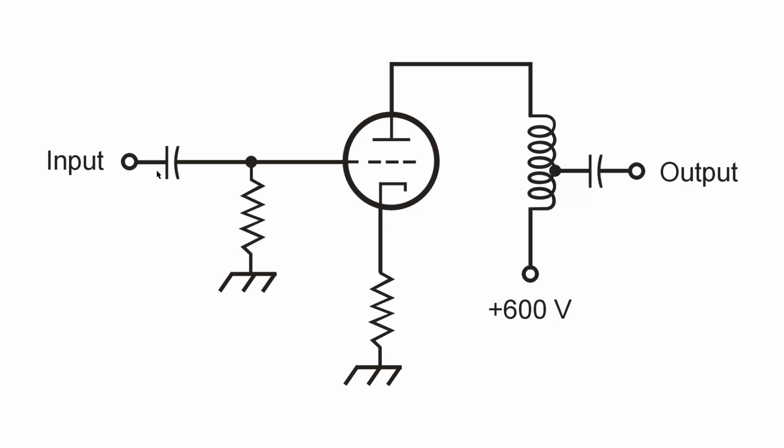And as this signal alternates, passing through this blocking capacitor, and changes the voltage on this control grid to more negative, then less negative, then more negative, then less negative, but always negative with respect to the cathode, you will get DC modulated by the audio frequency or by the radio frequency signal. Well, it could be audio frequency just as well, but because this is an open air core transformer, you can be almost certain it's a radio frequency amplifier.